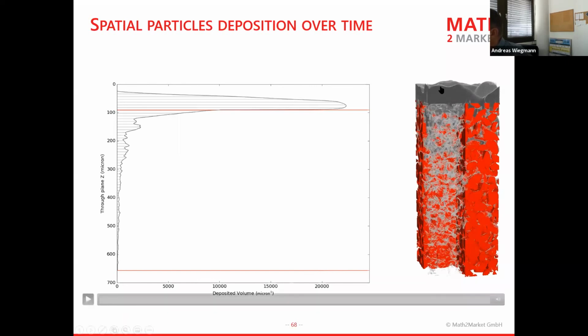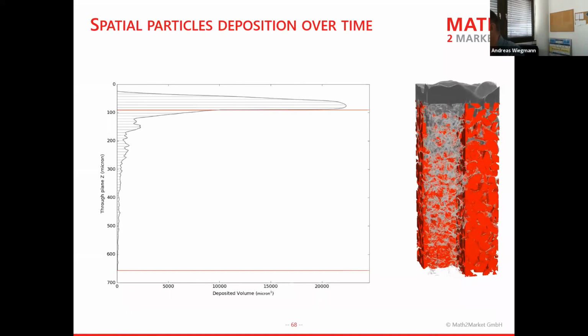The flow still goes through the captured soot up here, because that's a porous media that's being formed, and then there's porous media forming in the pores in here that allows flow through it, and you have to model how particles may get captured also in the porous media or not. We have several, but this is one of the more complicated processes on which you might want to do a design.